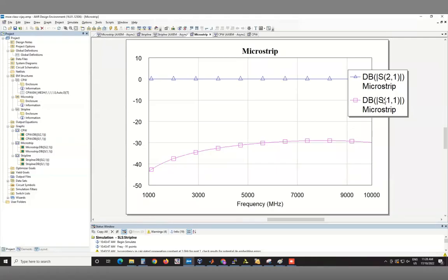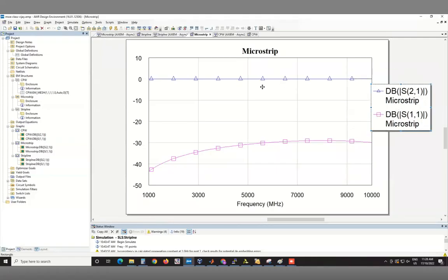So here are the scattering parameters: S21 transmission and S11 the reflection. Please note it's in dB units. You should also get used to seeing these numbers. Unit transmission means 0 dB, log units, and this is sort of orders of magnitude. The reflection is near minus 30 dB or below, which means this is 10 to the minus 3 or lower. So these are very, very small numbers. So it's good. Basically, this is 1 and this is effectively 0 if we look at the linear units.